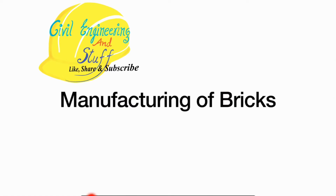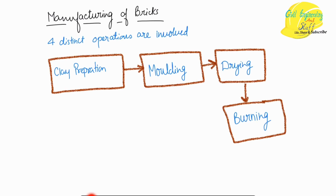Hello everyone. So continuing from the previous lecture on bricks, today we are going to discuss the manufacturing of bricks. The manufacturing of bricks can be broadly classified into four different stages. The first stage is the preparation of clay. Then the second stage is the molding process. The third stage will be the drying of the mold that we have prepared, and at the last will be the burning of the brick molds that we have obtained, so that the required hardness can be obtained.